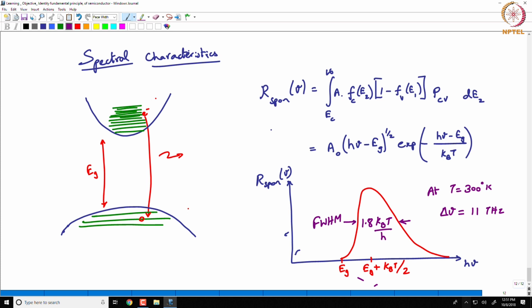And how are we getting white light, which is spanning 400 to 700 nanometers? It's because on each of those LED elements, there is actually a phosphor coating. That phosphor coating gets illuminated by UV light, very much like your old fluorescent lamps. You will have a phosphor coating on the inside, so you will emit white light.